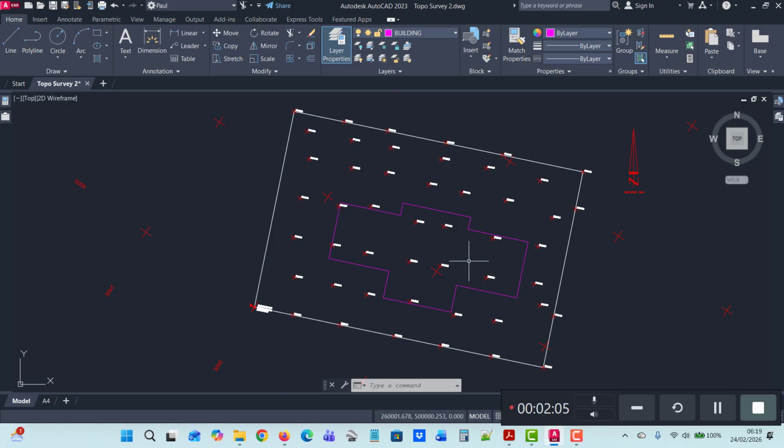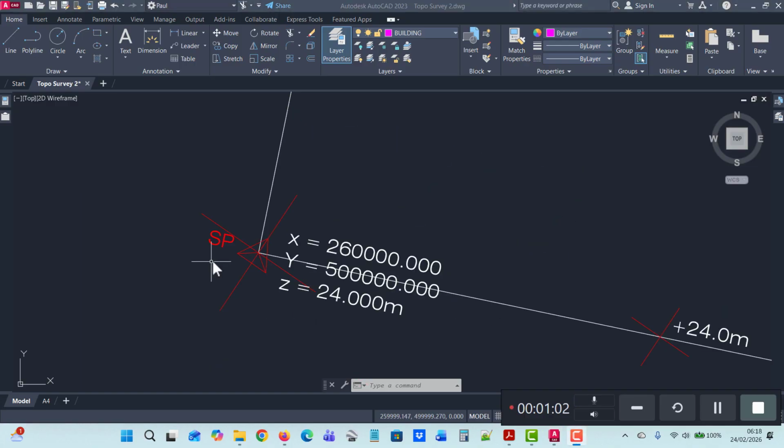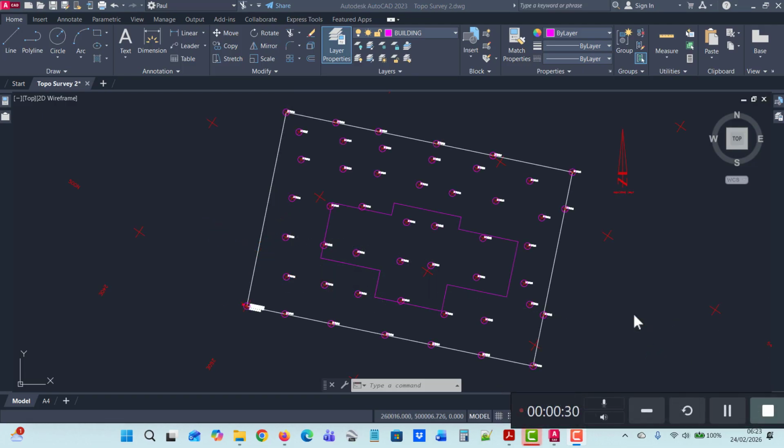If that's the case, you still have all the topographic information you need on the AutoCAD file to make your own XYZ file. All you need is the station point, the X and Y coordinates, and the AOD of every surveyed point. First thing I'm going to do is place a circle with its center directly onto each survey point.